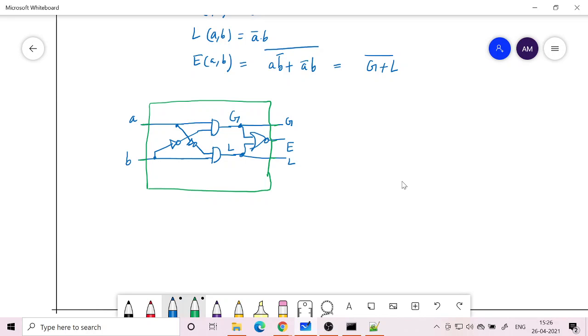So now I want to test it. What do I need to do? One way, if this hardware is before us, is that we need a power supply for testing it, which can supply 0 and supply 1, so logic 1 and logic 0, and I have to basically test the truth table.